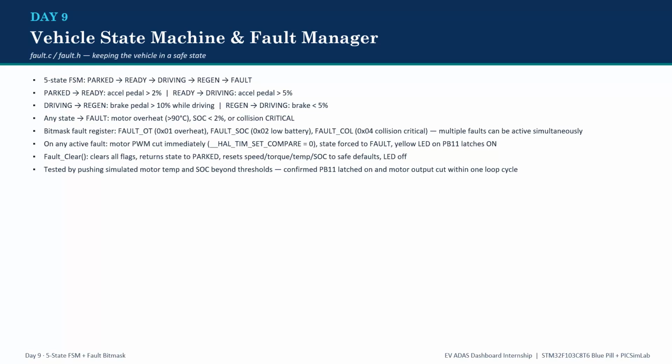The vehicle has 5 states: parked, ready, driving, regeneration, and fault. The transitions are specific. Parked moves to ready on the accelerator pedal. Once the accelerator pedal exceeds 2%, ready moves to driving. Once the accelerator exceeds 5%, driving moves to regeneration.